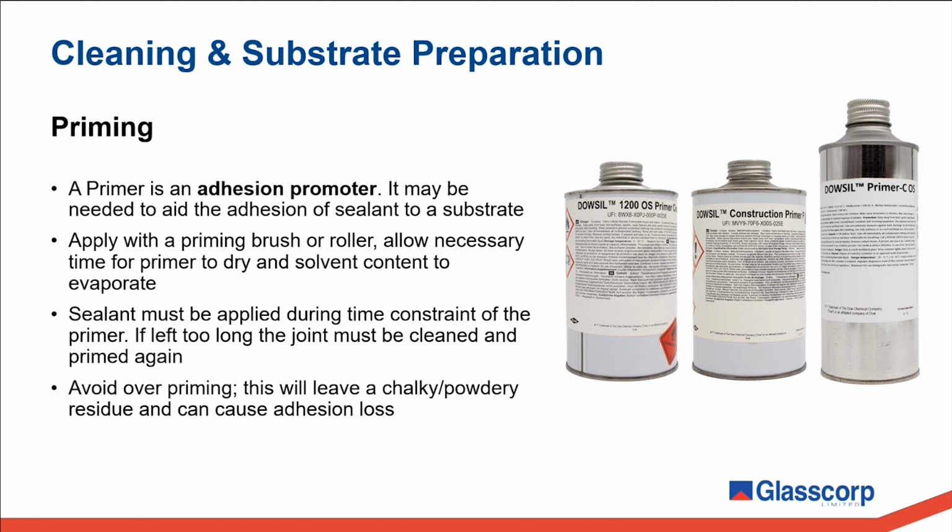And finally, it's important that you don't overprime. So when you see a chalky, powdery residue left on the surface, that may be a sign that too much primer has been applied, or that the primer has expired and is no longer suitable to use. In either case, there's a risk that this will inhibit adhesion and not help it. So for those reasons, and what I've described above, the additional amount of care required when priming, we don't normally recommend it unless testing has shown that it's absolutely necessary in order to obtain consistent adhesion.